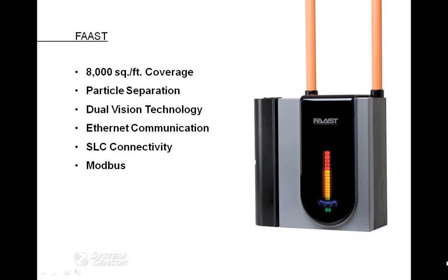This particle separator actually forces the airflow to make a dramatic turn, and only small particulates like those associated with particles of combustion are really going to be able to make that change in airflow direction. This automatically voids the air sample of any large particulate through the exhaust before the sample in the chamber can actually be contaminated.